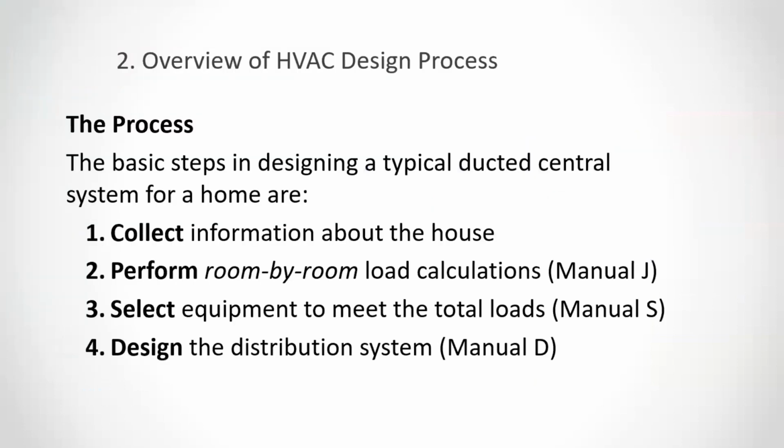All right, next slide. So the four basic steps: collect information about the house. Perform room by room load calculations. That's where you need good software. Then select the equipment based on those loads, and then design the distribution system. Okay, next slide.